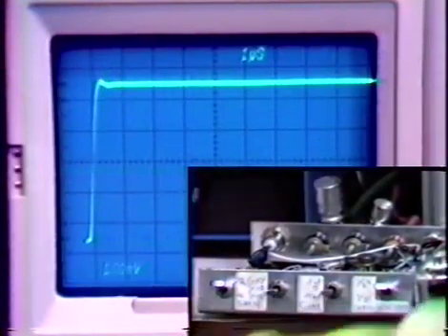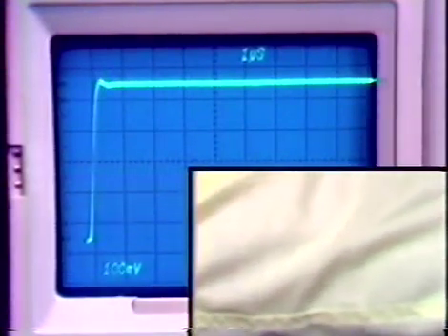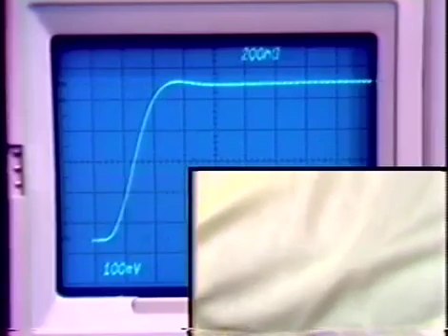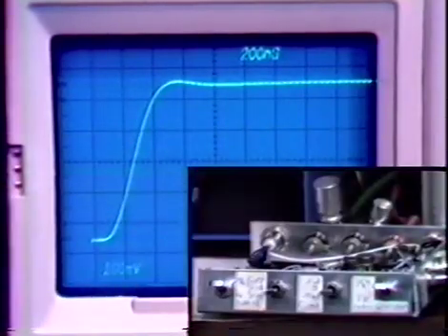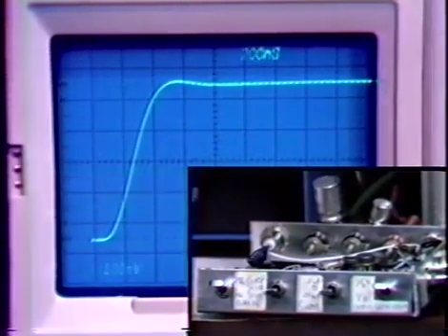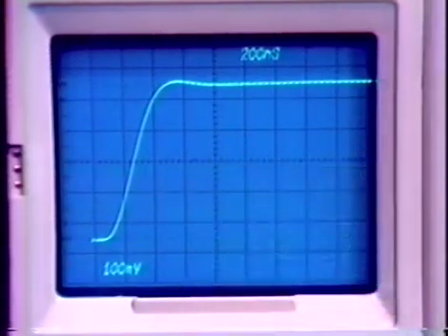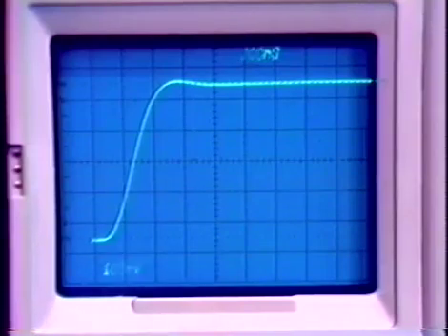And we find out that we get a response that's very similar to the original one. Here we have just a little bit of overshoot. So we're back to corresponding to stability, actually probably a little bit better than the original one. This capacitor might be a little larger than the one that would give us exactly the same amount of overshoot as we got in the first experiment.